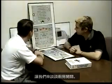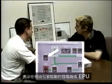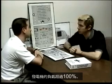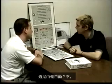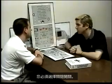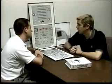Let's talk about the galley switch. Fault in the galley. What does that indicate? Indicates that any engine-driven generator or the APU generator has a load in excess of 100%. Doesn't it shed the galleys completely? Or by shed automatically? No, the galleys are not shed automatically. You have to select the switch to off. And then what occurs? The galleys are unpowered.